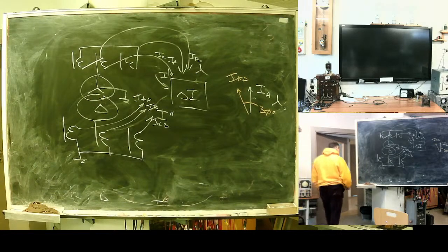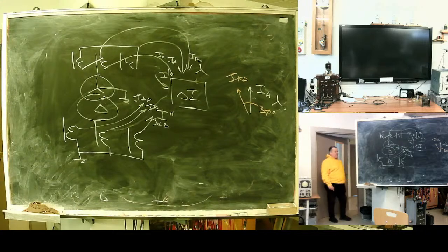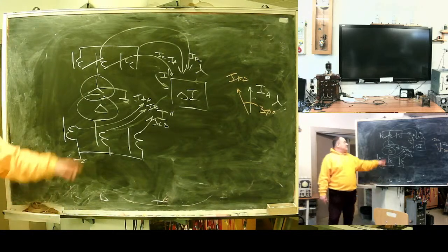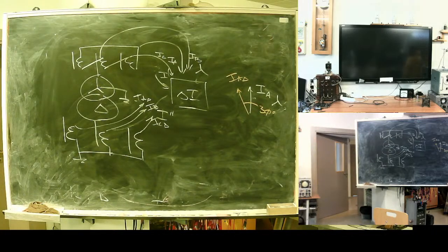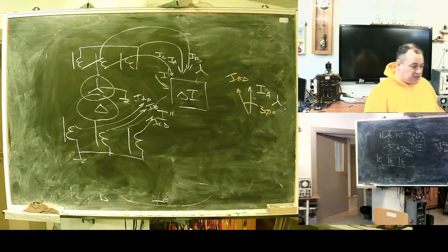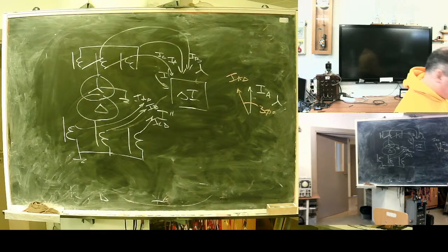Okay, when we speak on differential protection, I will explain this deeper. But delta connection of current transformer can be used to compensate phase shift introduced by connection scheme star delta of the main transformer.